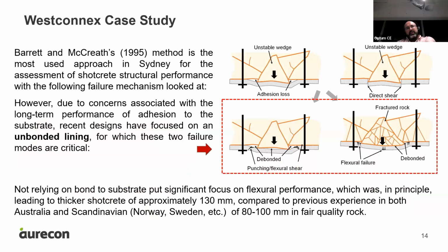Now, how do we design this shotcrete? Shotcrete, or sprayed concrete, as I said, the name is sprayed. The nature of spraying means that I have to have a mix that's able to stick. Once I spray, it needs to stick to the rock, it needs to stick to the ground. So obviously we design with the intention of having good adhesion or good bond capacity.